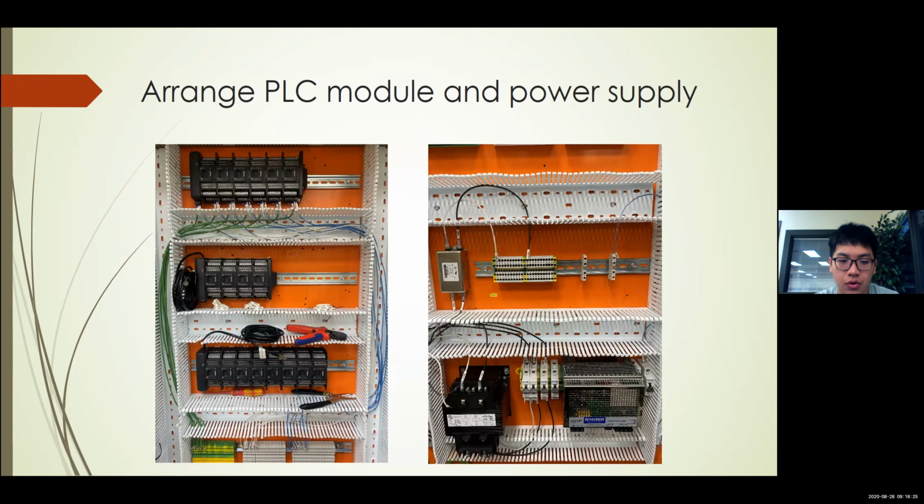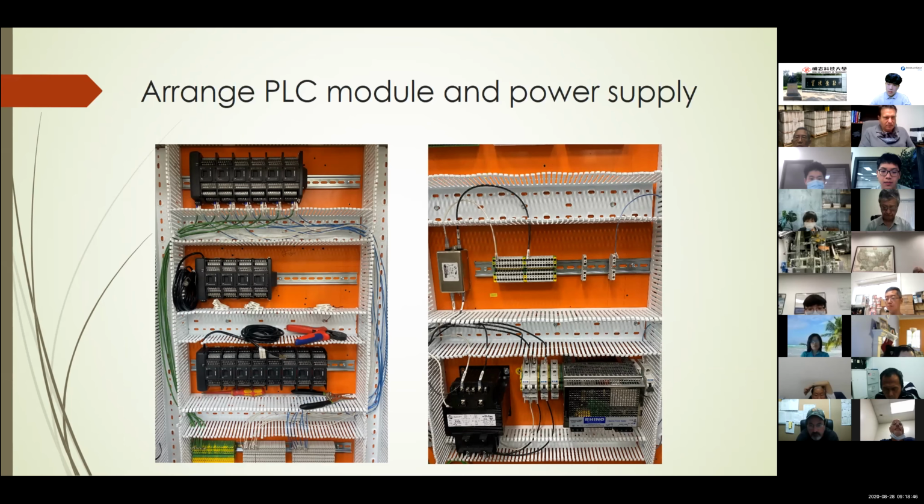We organize control wires and signal wires through the PLC, and then go to different control panels through terminal blocks. In this way, the wiring is easy and makes the inside of the panel look neat. Even though some wires may be wasted, we also gather all power supply wires together. Basically, all the direct current in the room comes from here.